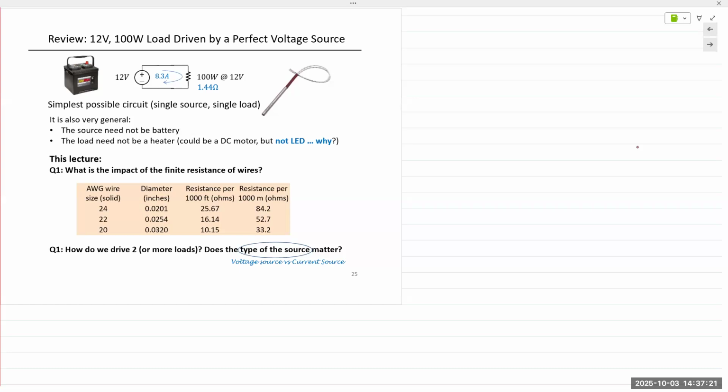Line voltage never stays the same. It fluctuates. So even though we say it's 120 volts, it could fall to 110. It could even fall to 100 volts sometimes, depending on the loads. So even if the line voltage falls from 120 to 110, even to 105, or even 100 volts, your laptop chargers and your phone chargers will still work. If it falls to 90 volts, now they will not.